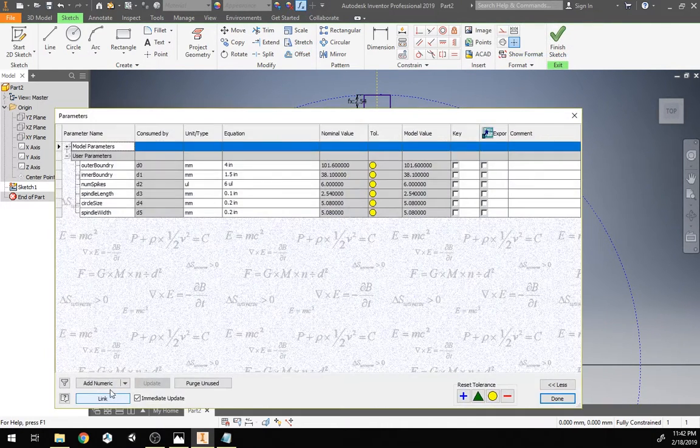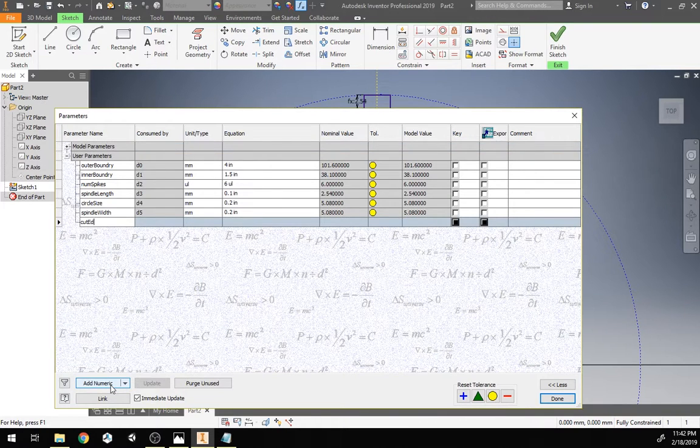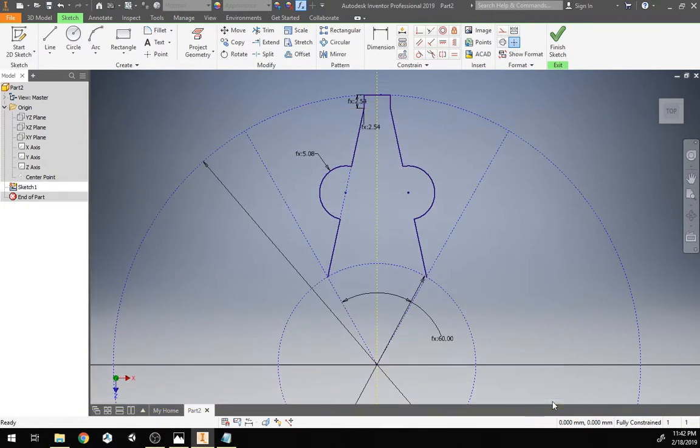I'm going to go to the parameters, and then I'm going to say the cut edge thickness. And I think a good cut edge thickness is let's do 2 millimeters. And the nice thing about this is you can mix up units, for better or worse.